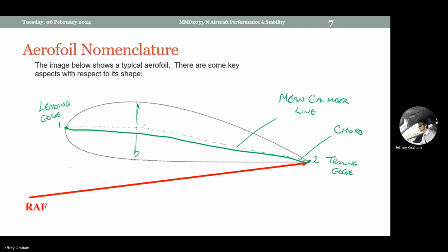All right. And as I say, I've already spoiled some of these in what I've said earlier on, but the maximum pressure or pressure differential occurs at the thickest point. So it's roughly where I've drawn this arrow incidentally. So this is the maximum distance from the top of the airfoil to the bottom, often given as part of the NACA number of an airfoil. So that is where the code comes from. So we've got the thickness.